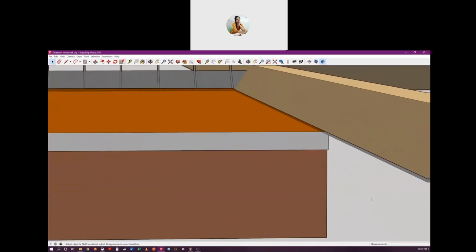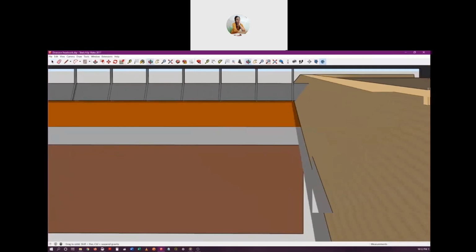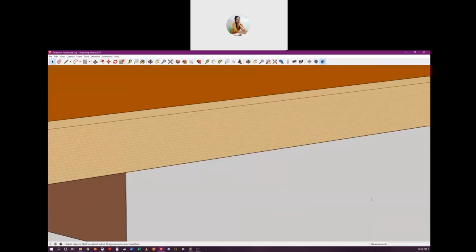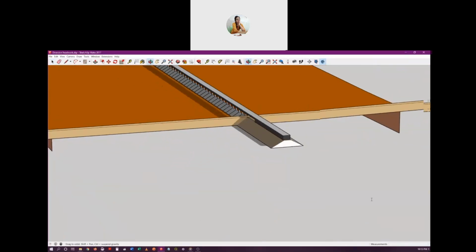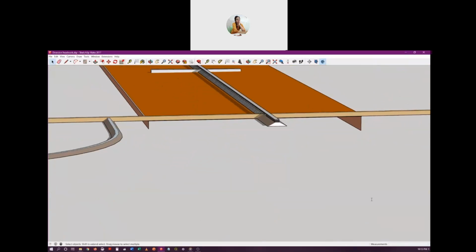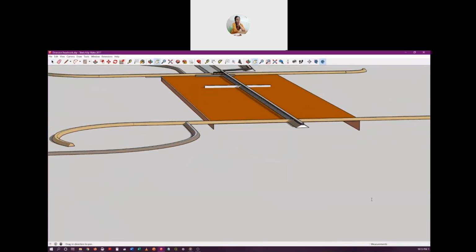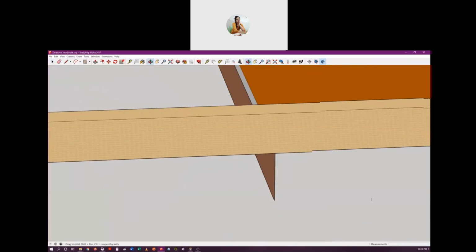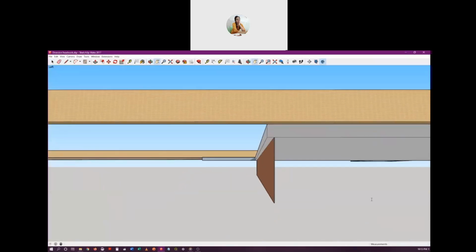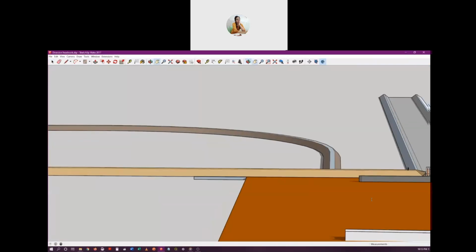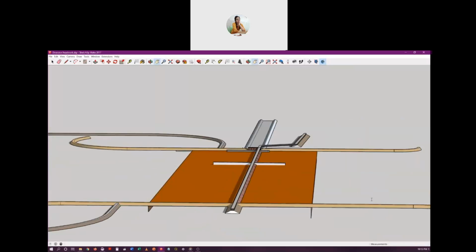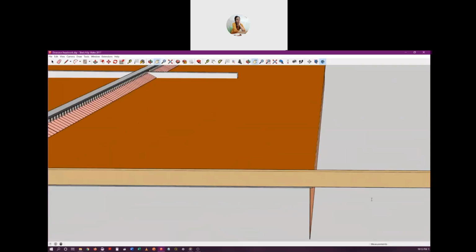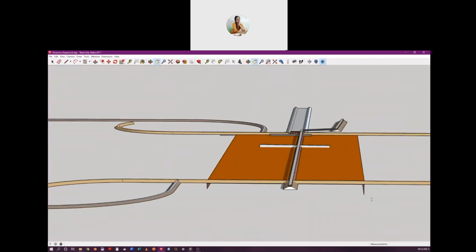These are provided here so that water doesn't simply flow straight from this point to the downstream end of the impervious floor. And because of provision of these kind of cutoffs, they'll have to take a longer path. They have to first go down, then up, then again horizontally, then again in this cutoff they'll have to go down, then up. So it increases the length of flow.